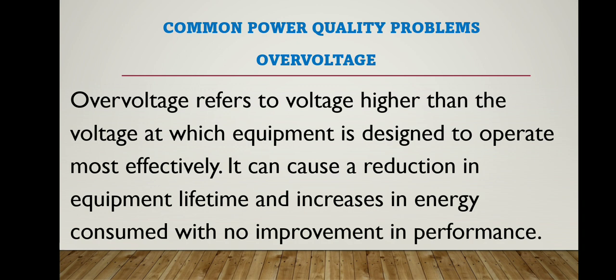And the most common power quality problem is over voltage. Over voltage refers to voltage higher than the voltage at which equipment is designed to operate most effectively. It can cause a reduction in equipment lifetime and increases in energy consumed with no improvement in performance.